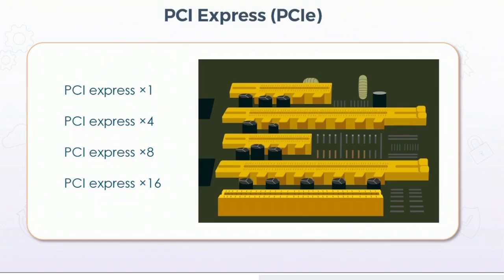That said, for just PCIe slots themselves, devices with the smaller interfaces, and therefore those that are meant to be installed into the smaller slots, can in fact be installed into the larger slots if need be. Once installed, the device and the interface will auto-negotiate the maximum number of lanes that can be supported. So if, for example, a 4-lane device is installed into an 8-lane slot, it will still work, but only over 4 lanes.